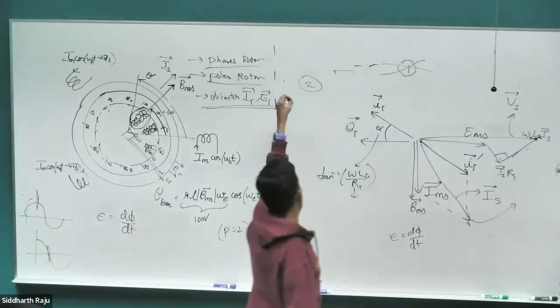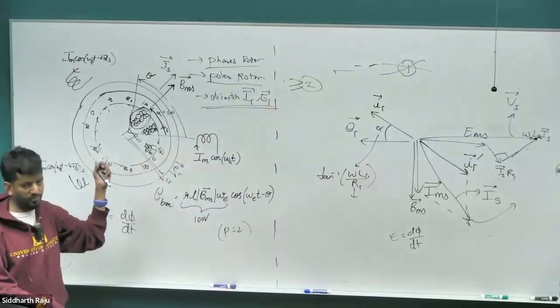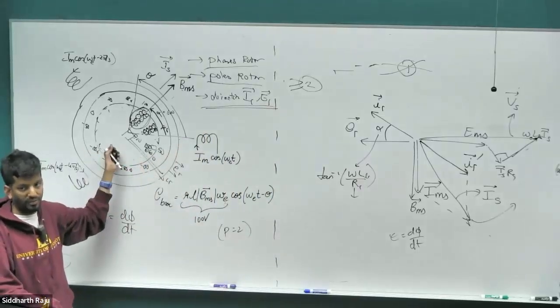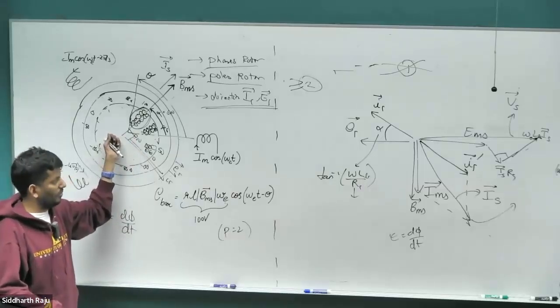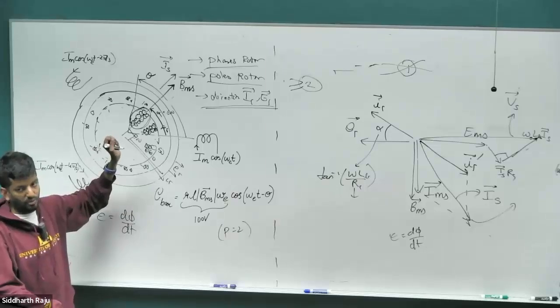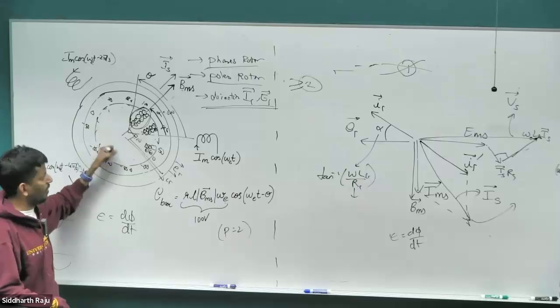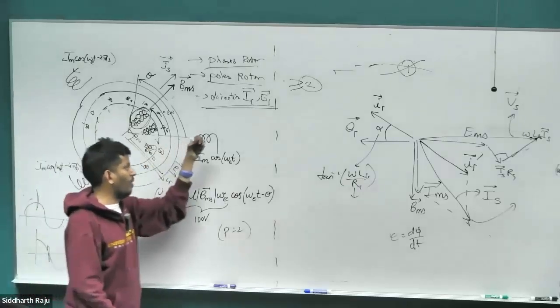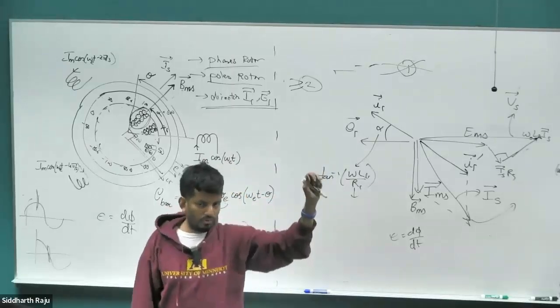Any more than 2? So there is no requirement that the rotor has phases; there is no concept of phase on the rotor side. Going back to the question that Ben had asked, what does it mean by phases on the rotor? There is nothing meant by phase on the rotor. There are no terminals coming out, nothing is happening there. But if you want to model mathematically what's going on in the rotor, you need to model it as some polyphase circuit, either 2, 3, 4, 5, whatever you want to choose.